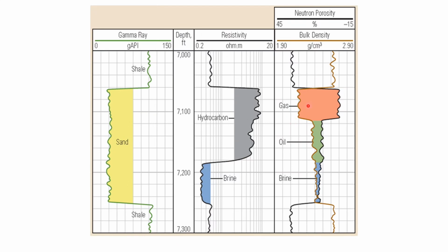To find the effective porosity, we go for the normal resistivity logs. To find the shale or clay content, we go for the gamma logs. To find the permeability, we can go for the porosity log or the sonic log, and to locate the water level, we go for the electrical log or temperature logs, and in that you have many different kinds of logs.